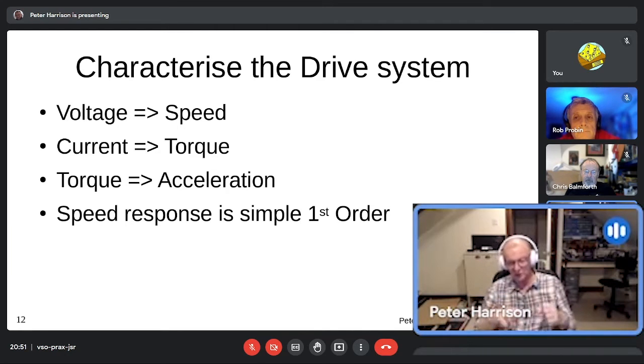If you want to get up that hill, in a car, you've got to apply more torque, and that would mean putting more current into the motor. So in order to go 1 meter per second up that hill, you'd still want 4 volts on the motor, but you want to be able to provide more current behind it. I don't know if that makes sense. If it doesn't, don't worry about it, because it's a distraction. But this is the rule, okay? Voltage determines speed, current determines torque.